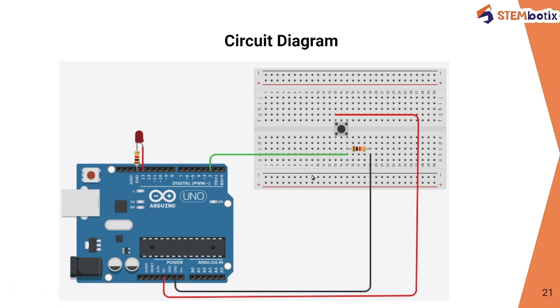Now the next is to connect it on the digital pin in order to take input from this, because using that input mode we need to operate our LEDs accordingly. Here we have connected only one LED in order to control it using push button. Hence use this terminal and connect this terminal to the second digital pin of Arduino Uno. So the digital pin number 2 of Arduino Uno is connected to the push button's one terminal.